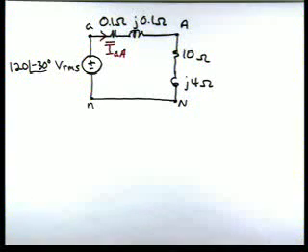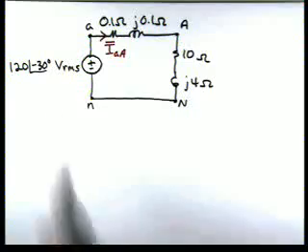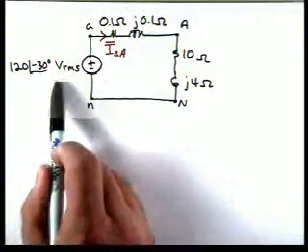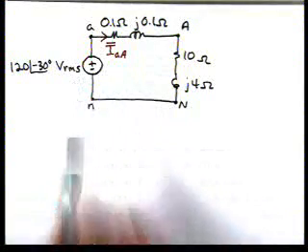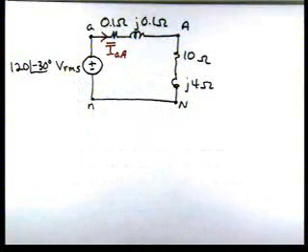Here we've just drawn the A phase. Here's our voltage VAN. Here's our load. Here's a line, and remember we had to convert this to a Y. We originally had a delta connected source. So now we can analyze this per phase circuit.